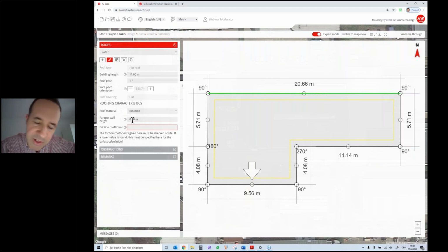We know, like I said, the averages, but we encourage each and every one of you to just measure this each and every time. I will take an average. I have measured this in the past. So for a bitumen-based ply membrane, I would enter 0.65. It's the average, but it can swing back and forth by 10 or even more, depending on the manufacturer and the type of the bitumen-based ply membrane. So for the sake of the exercise, I'm just going to leave 0.65.